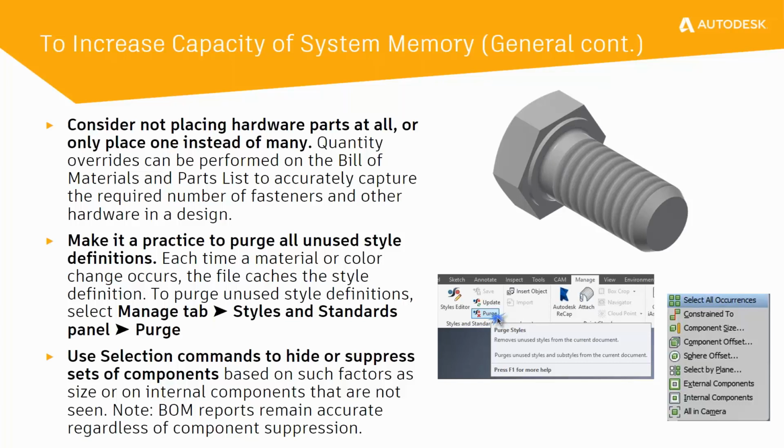Make it a practice to purge all unused style definitions, and you can do this from the Manage tab, Styles and Standards panel, Purge. And this is a process of purging any unused styles. And also use the selection commands to hide or suppress sets of components, and we've talked a couple of times about those in today's webinar.